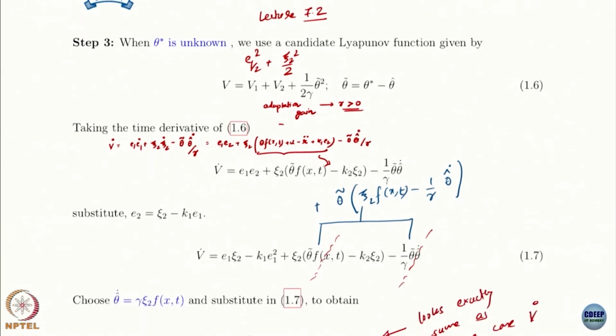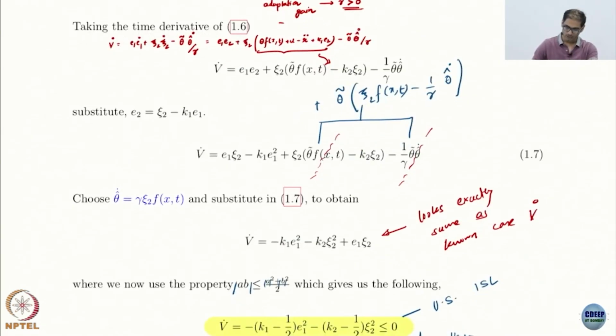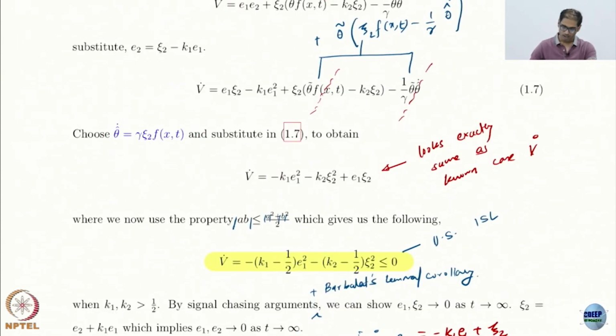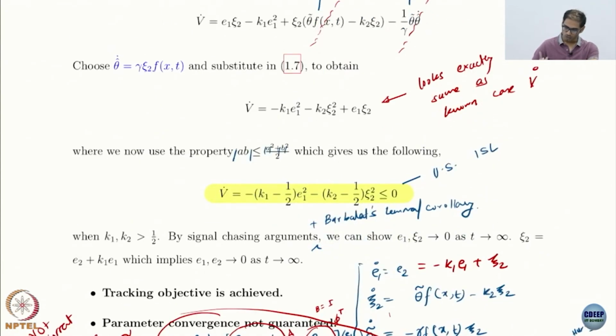And then we did the analysis, and the purpose of this analysis was to get an update law. We got that. The really cool thing, like I said, was you don't care where you start this update law, right? You don't care about the initial condition. It can be anything. It can be as far from the true value as you want. You will still get exact tracking. This guarantees that you get exact tracking, okay, and that's pretty amazing if you ask me, right, because you made the system agnostic to the unknown, however much it was.